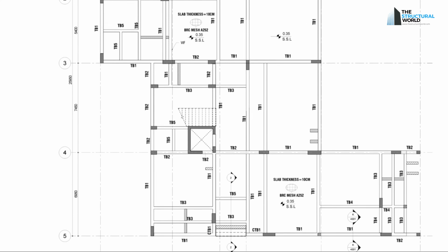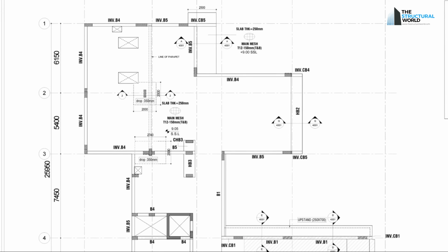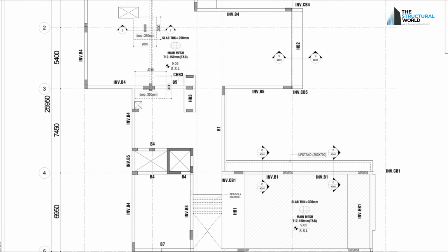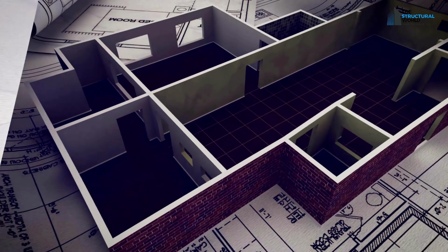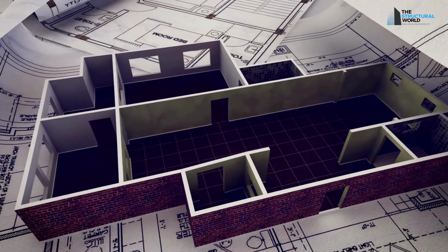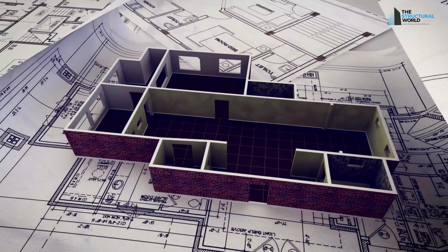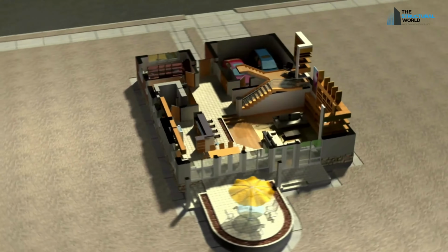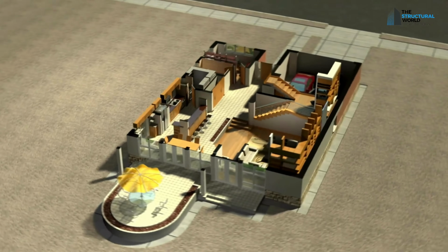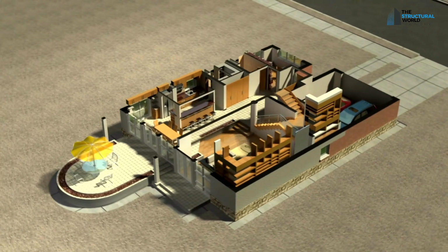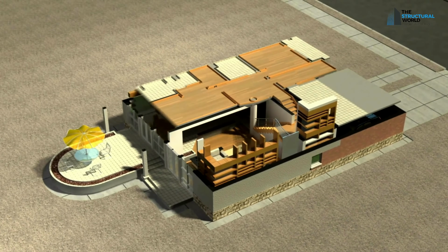GA plans are comprised of tie beam layout or ground floor framing plan, the typical floor framing and roof framing plans of the project. When reading, imagine you're looking on the top of the floor level it represents. Having the same north direction, all the arrangement and layout you can see when looking from the top is exactly the orientation of when constructed.